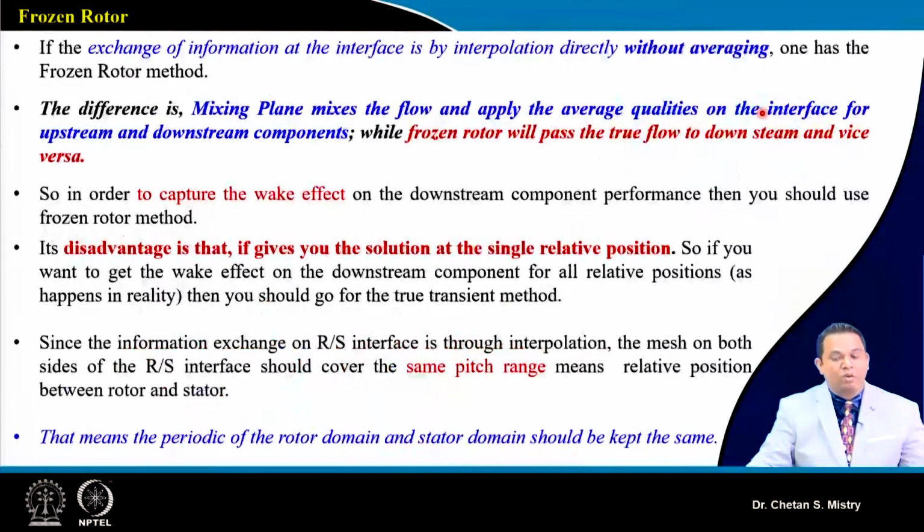Okay. Now in order to capture this detail, where we can capture our flow separation, our secondary flow, and our wake formation, we need to go with a different approach. That approach is called the frozen rotor approach.